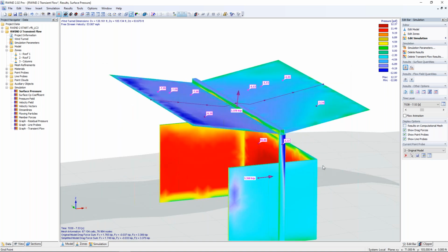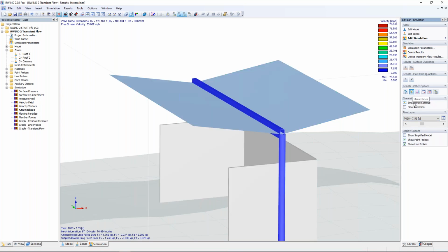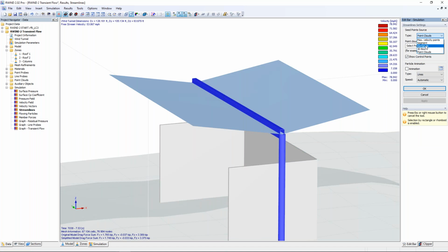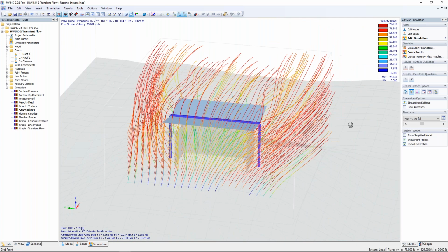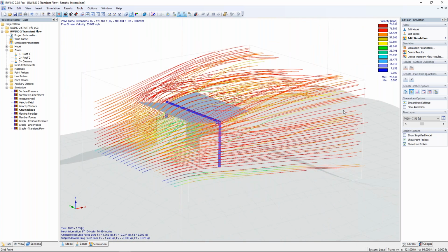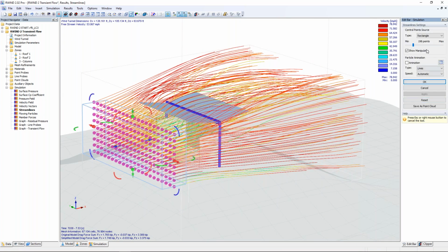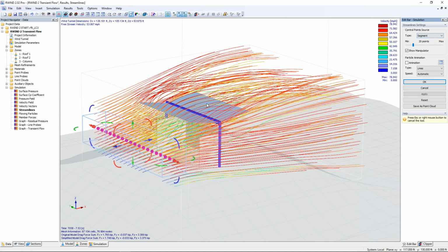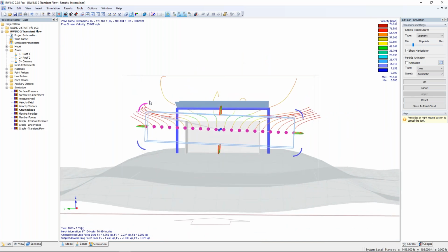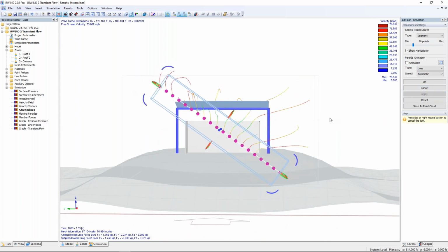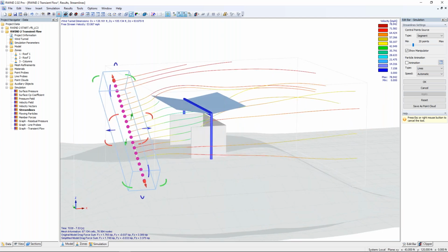Okay, so the final results option that I want to show you that's new within RFEM is called point clouds. And we can activate here our streamlines of our structure, and the typical default option would look something like this. So the streamlines are kind of just based on this rectangle in and around the structure. Of course, we can activate the streamline settings here to change this to a segment, for example. We click apply, and now we have a single kind of line element here. We can use the graphical options to rotate this, hit apply, see how those streamlines are changing graphically.